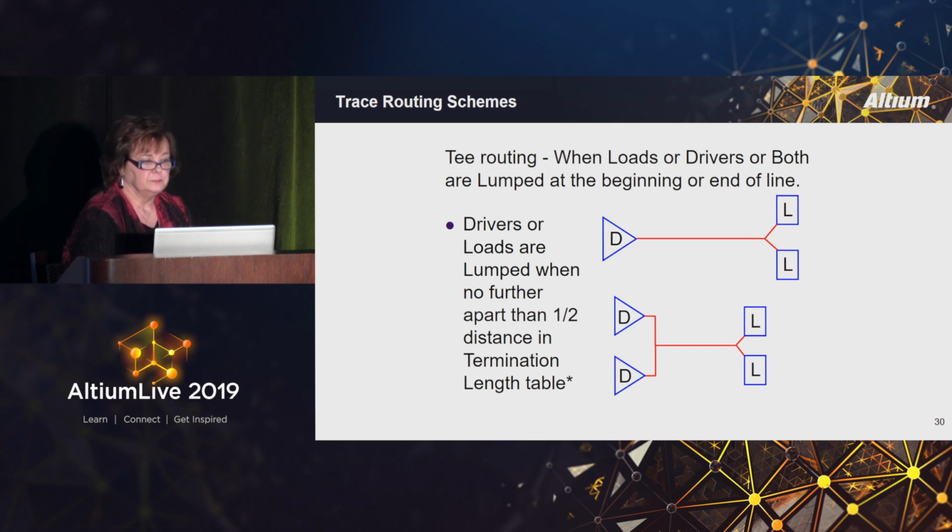So T-routing, as I mentioned before, has a driver or multiple drivers and a load or multiple loads, and you group them so close together that they look like a lumped load. And there's a termination table that I borrowed from Rick that's a few slides back from here. And so what you want for the lumped load is for the drivers or the loads or both to be 1/2 the distance in the termination table. And that can be very, very, very short the faster your signals are transitioning. So you have to understand that you have to put them very close to one another in T-routing.